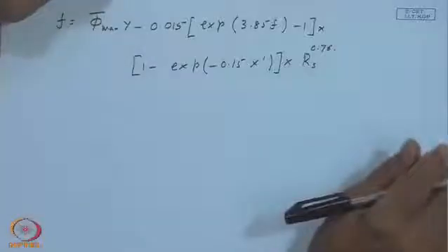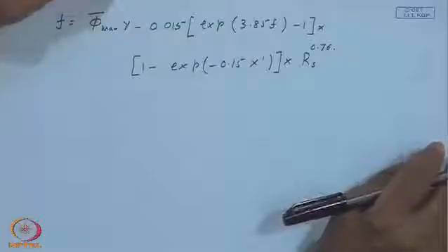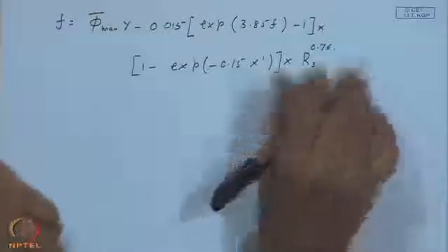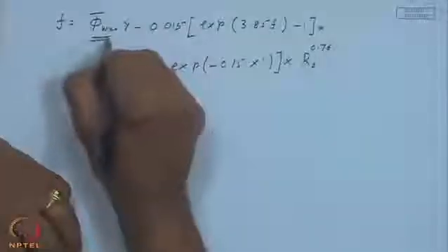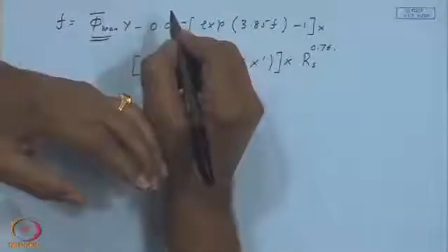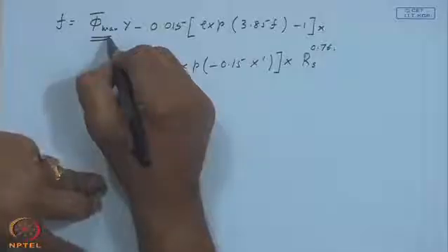We have done up to here, and we tried to describe how to include the tank losses also in brief in the last class. But my whole idea is, the philosophy behind this phibar F chart method is to relate the temperature at which energy delivery is desired to the minimum temperature and a quantity called utilizability, which indicates the solar radiation available above a certain critical level.